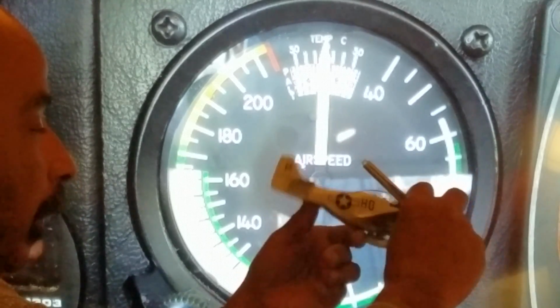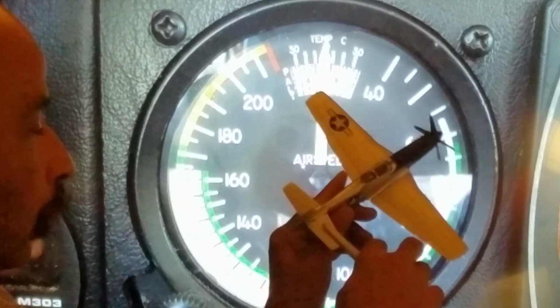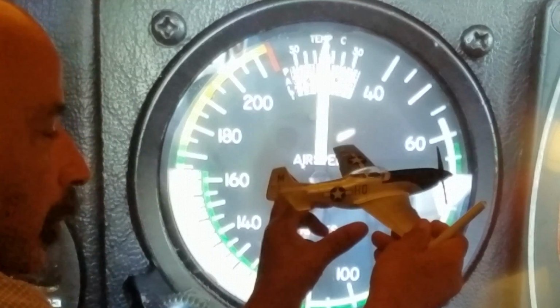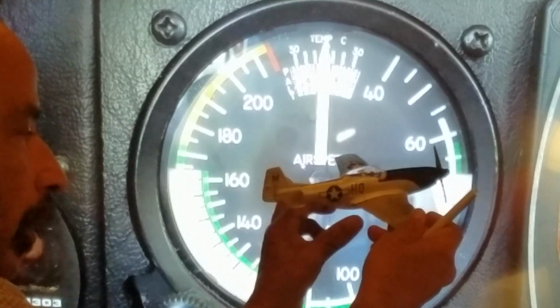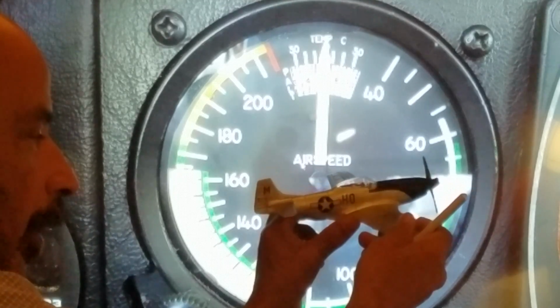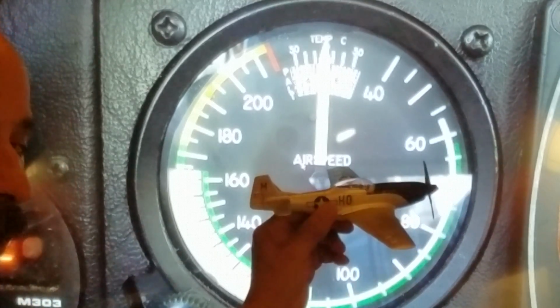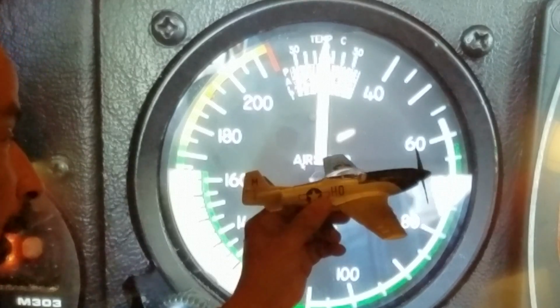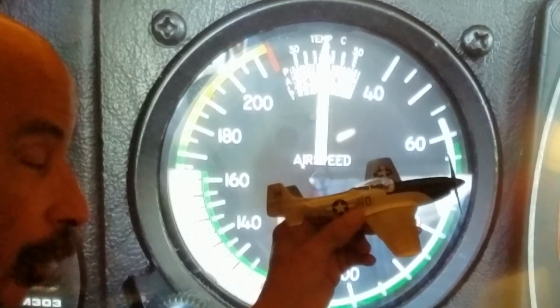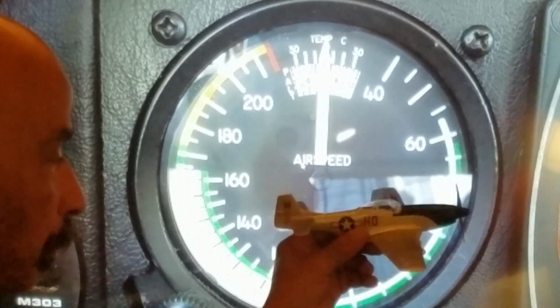When you extend the flaps, they come down together. Both flaps, left and right, will come down, and they act as a form of speed brake, but they also increase lift as they're first moving. But beyond a certain extension, typically 20 degrees of flap extension, they become more of a drag-inducing device, slowing the aircraft down quite a bit.